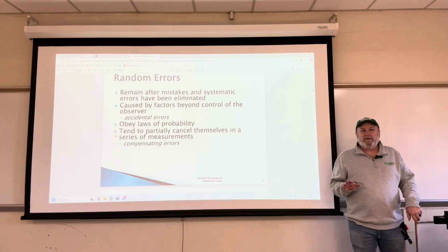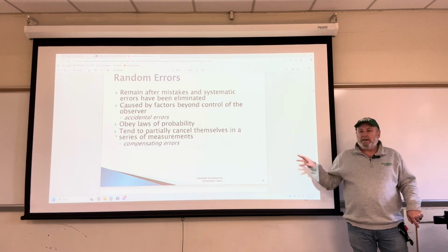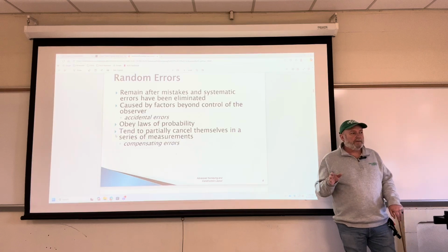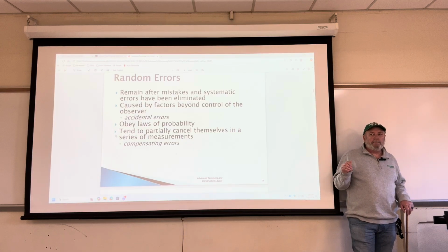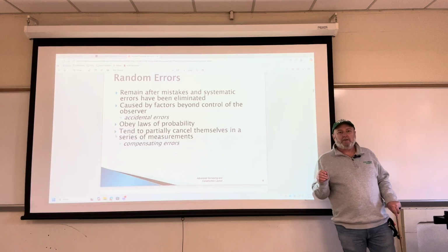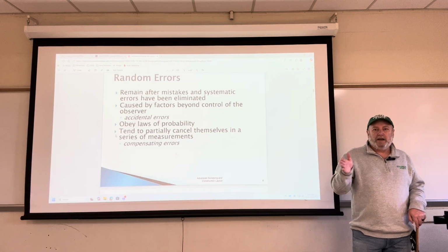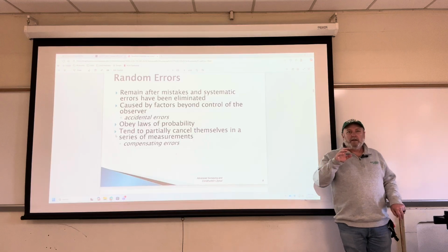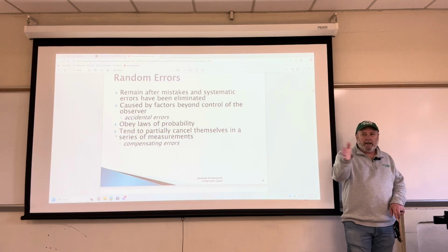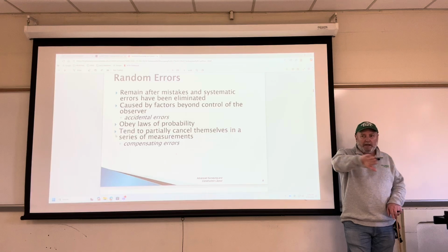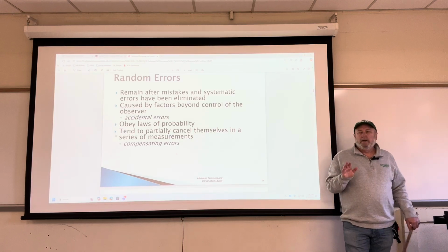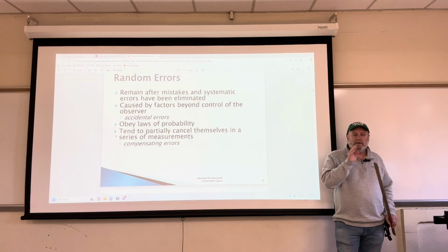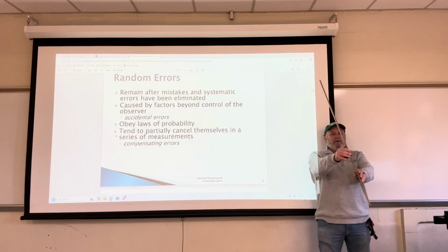To give you a little bit of a visual on that, we'll probably talk about it again when we get out and do some angular measurements. Maybe you guys remember from surveying fundamentals class when we did a closed loop traverse measuring the angles around a closed polygon. We doubled our angles, where we took an angular measurement, flopped our scope, and then took that measurement again. To exaggerate, if you're looking through the scope of your instrument and your vertical crosshair is